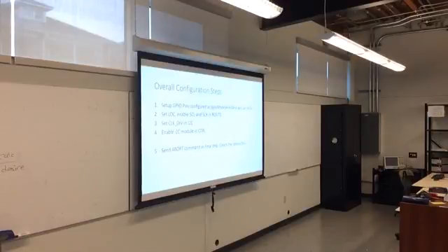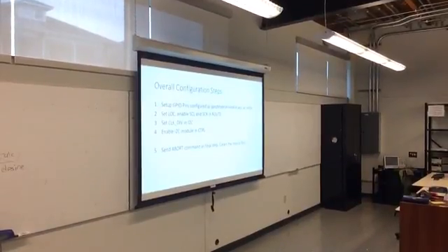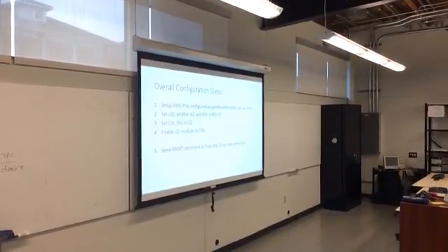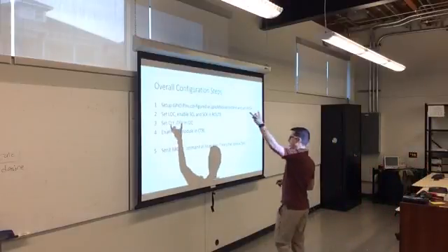As before, you've got a location register and a route register. Inside the route register, you can turn on and off your pins, and you can set which location you are going to use for your pins. We're going to use location 0. You've got to calculate and set up your clock divider, and then enable the I2C module in the control register. So it's really just four easy things to do, not that hard.